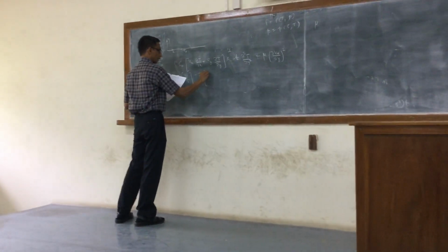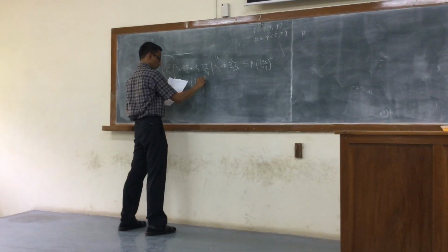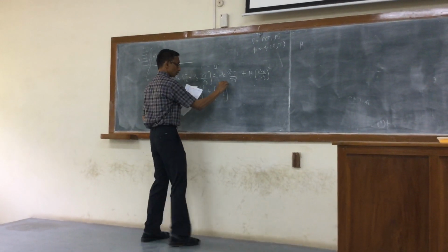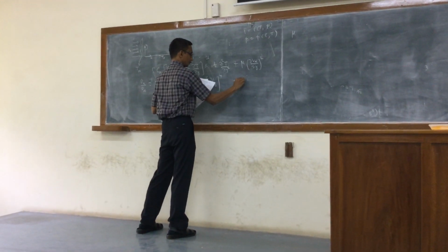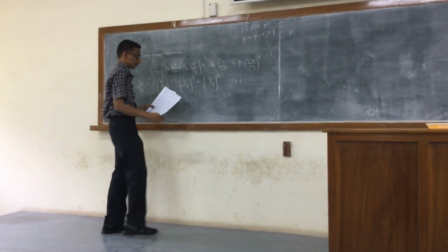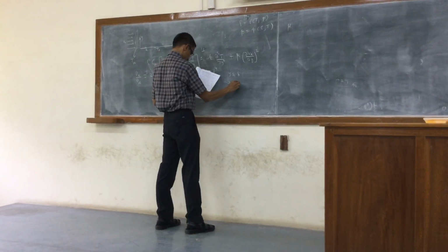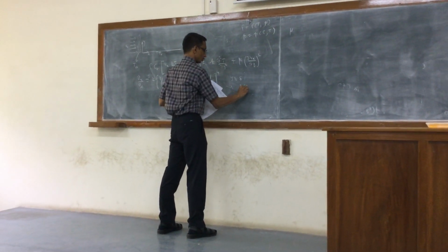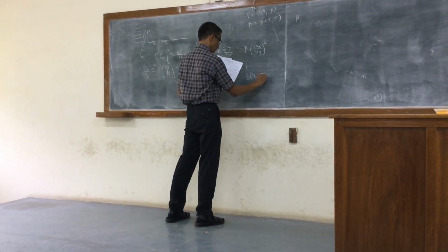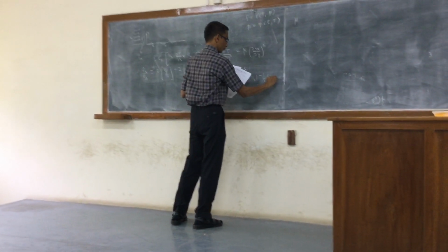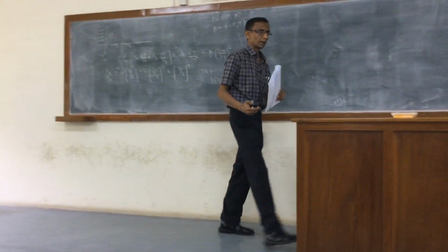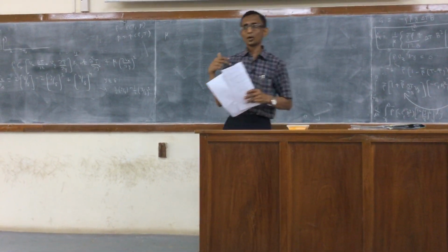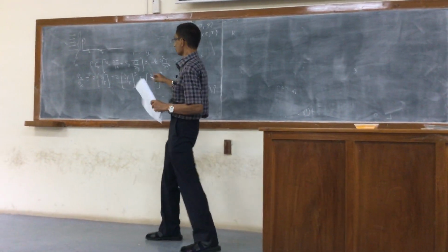What he introduces is a slightly different expression, where you have a combined effect of the hydrodynamic and thermal effects, for y less than or equal to delta. You compare this with what we had earlier, which was 3 by 2 y over delta minus half. He's saying that naturally, if you want to take the effect of temperature on the density term, that is going to modify.